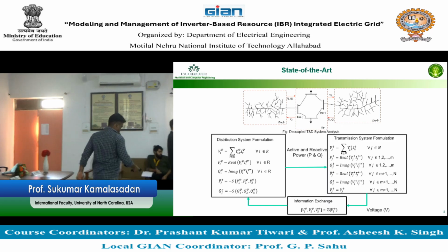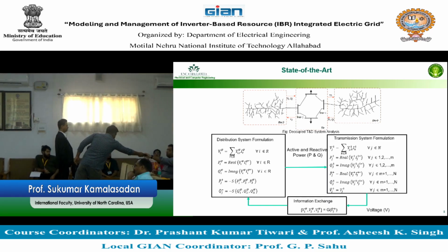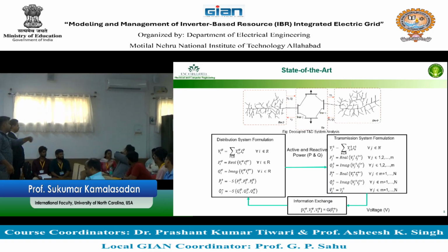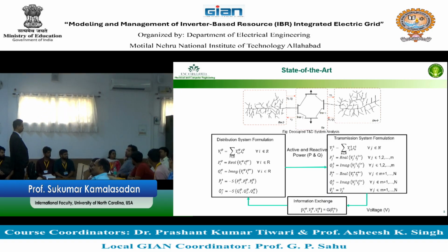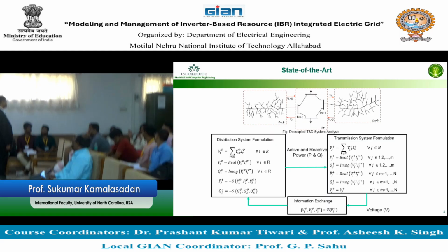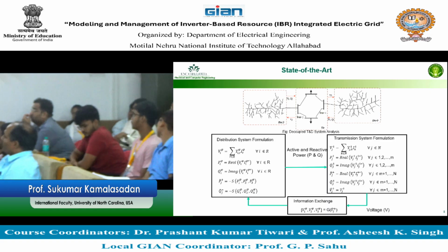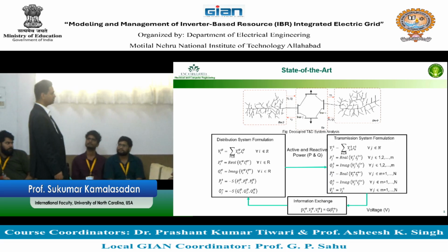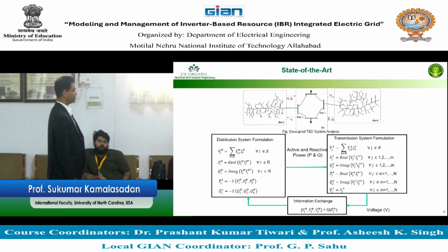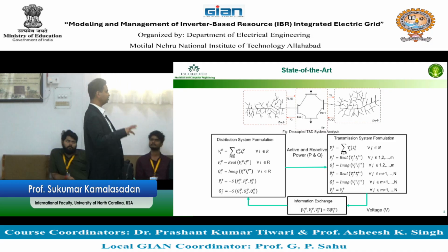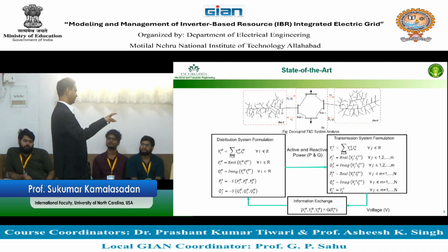So let's assume the transmission system load is 10 megawatt and 5 MVAr. Okay. If the distribution system representation is only 3 instead of 10, there are 7 ways to do it. But in a nutshell, my question is, will it come to exactly the same value? Means then you don't need to worry. Oh, you need to have exactly the same value? Yes, you must have exactly the same value, because the transmission system power flow is using that load.